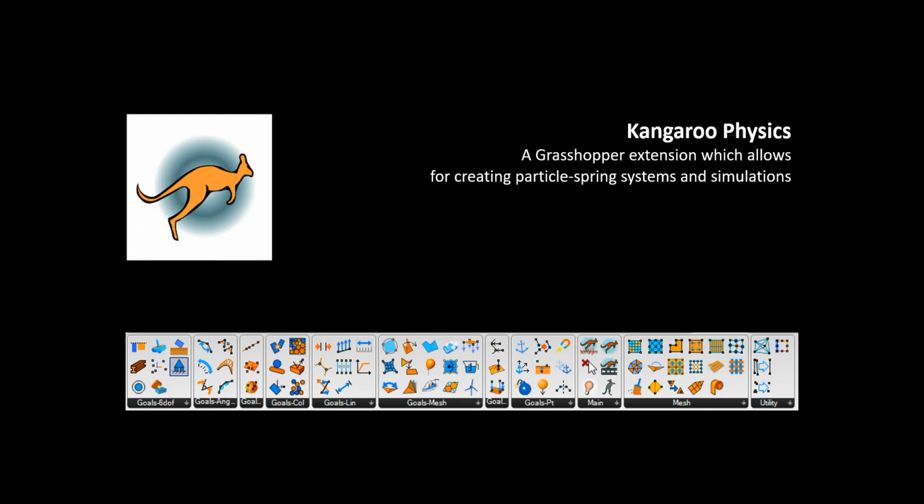It's used for real-time simulations of physics in Grasshopper. And those simulations are based on a particle spring system. Now I will explain to you how it works in detail, and then we will have a simple hands-on. In general, Kangaroo is a component that has a loop inside it. So it's like Anemone, but packed inside a component. It works on its own, and it has a few options about how it displays the process of the simulation.